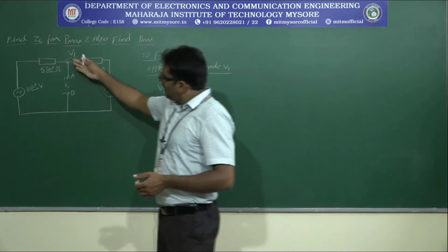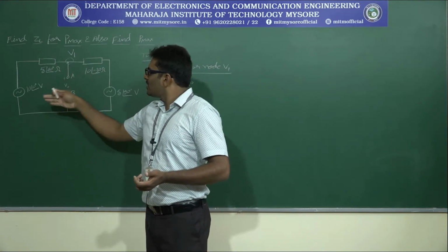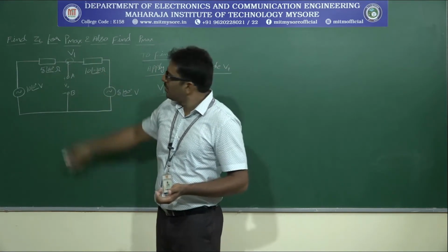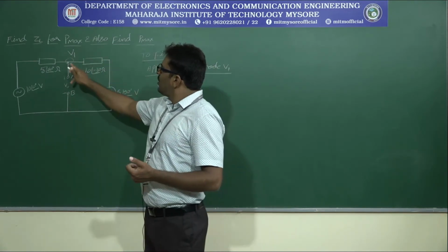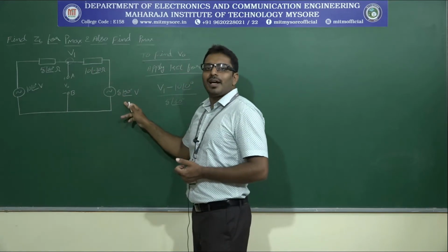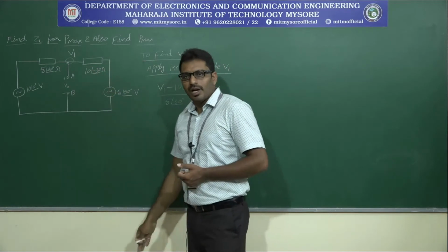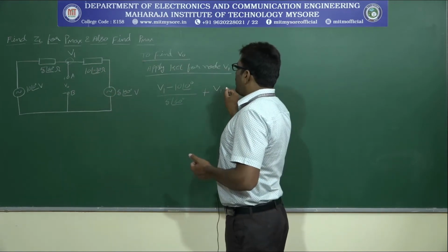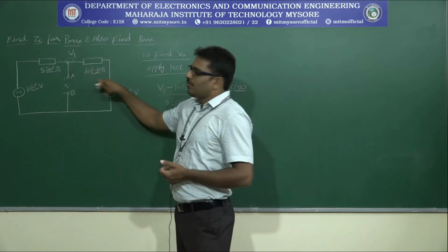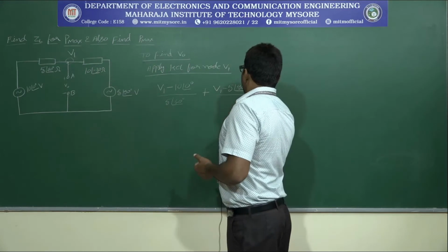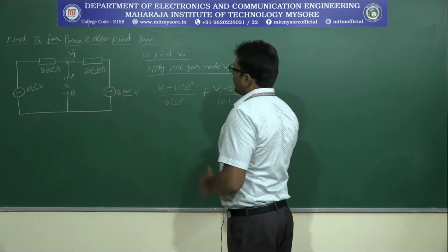Okay. Now what is the current in this branch? 0, because the load is already removed, right? When the load is removed, this path becomes open circuit. What is the current in this path? 0. So next, what is the current in this branch? V1 minus 5 at an angle 90, so plus, I am not going to write the 0. Okay. So V1 minus 5 at an angle 90 divided by, what is the impedance value? 10 at an angle minus 30, that is equal to 0.